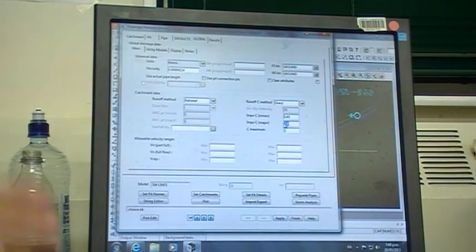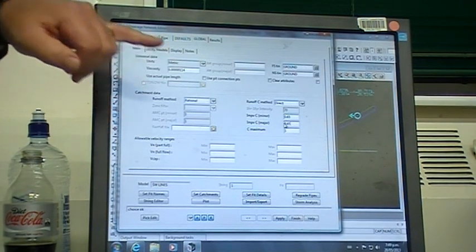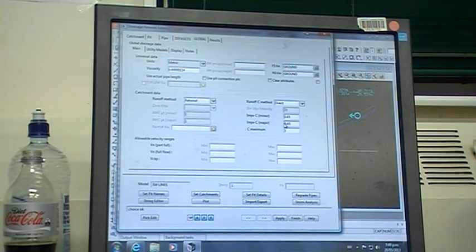Okay, it's not going to be relevant to something, but just anywhere you find that it asks you for a default value for pervious and impervious, just give it a blanket 0.65. Okay, that's all we're going to work on. That's what the council standards are, and that's based on X size of lot with X size of house on it, X size of paved area, a certain amount of lots per street. Okay, they've come up with 0.65 as a decent average number for them to use.